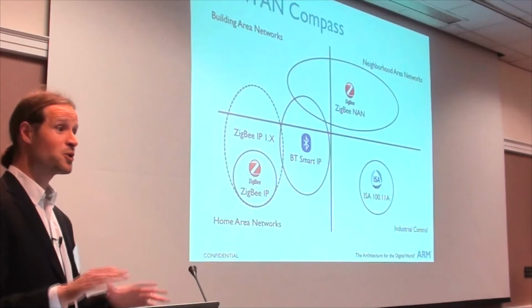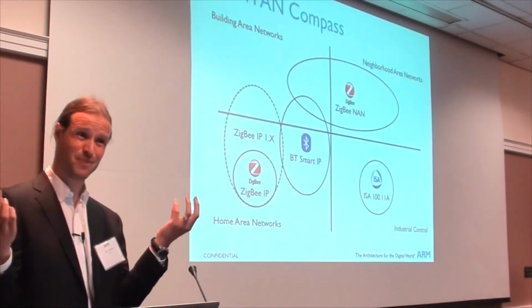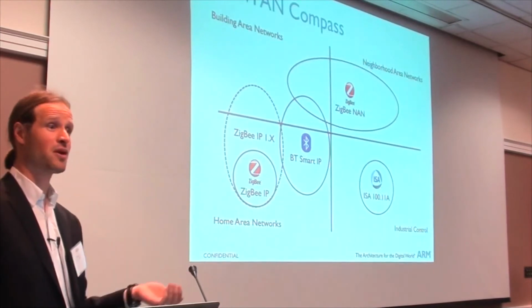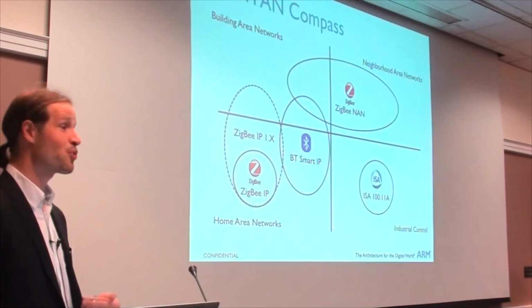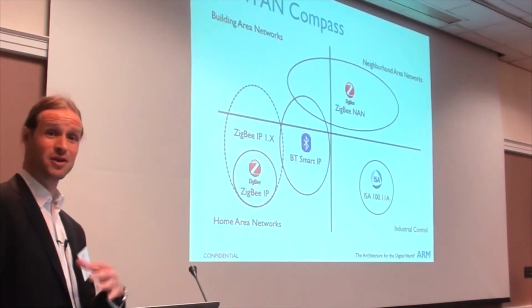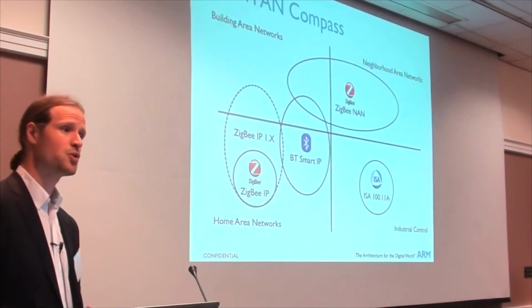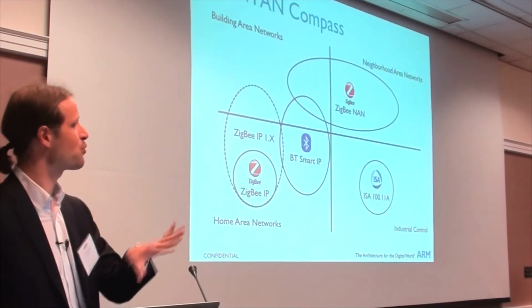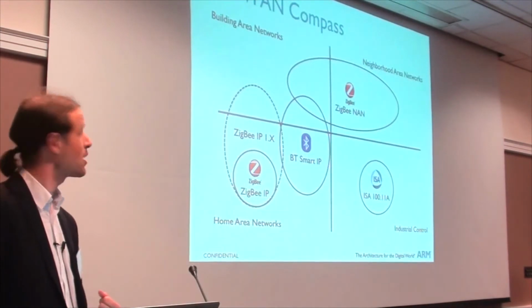The problem here, though, is we're not dealing with administered PCs, we're dealing with things, right? Street light, you don't want to have to go out and configure. So the way we handle that is through profiles. And surprisingly enough, the association that's got involved with profiles in 6LoWPAN is ZigBee. So in recent years, ZigBee's moved out of just proprietary networks into standard IP 6LoWPAN based networks.